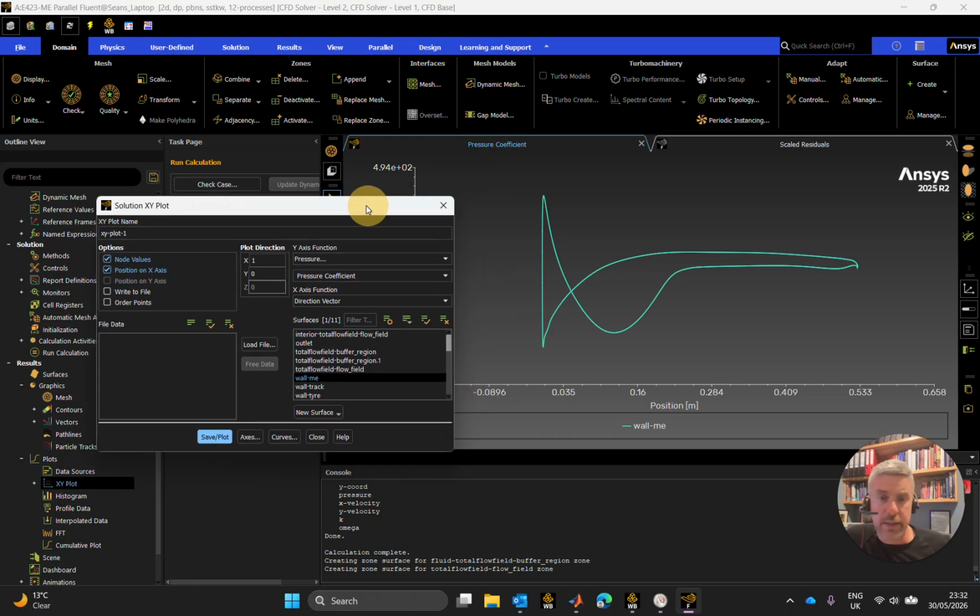So yeah, this single element front wing at that angle of attack for that velocity isn't optimal. All right, so our job is to find out how to optimize it, but the first thing we need to do is just understand what the angle of attack itself is doing. Most of the lift is going to be generated at the trailing edge of the wing, more so than the leading edge. So it is the trailing edge there that we want to deal with.